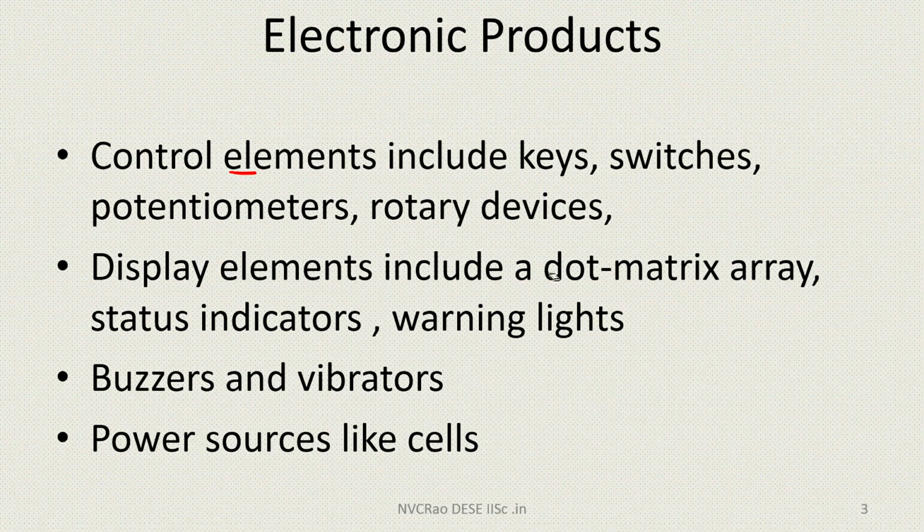And the moment you have this dot matrix display, I think a dot matrix array or anything else will probably need a transparent window through which we can look at it. And the moment there is a window, now suddenly everything inside is transferred to the outside. How do we treat that window? Do we need to provide a bezel all around? Do you need to put a mask, or what is it you do there?